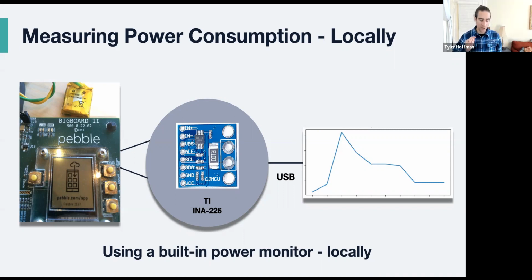And so you could measure how much current the battery chip was using, the accelerometer was using, the gyroscope was using, the compass was using, how much the flash chip was using. All these things had different channels, and it could export them individually on a running system. We had a couple of scripts that would allow you to plot in matplotlib on Python on your local machine and see that over time on an individual device.